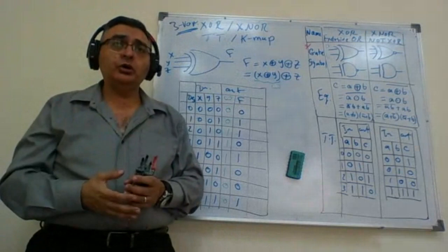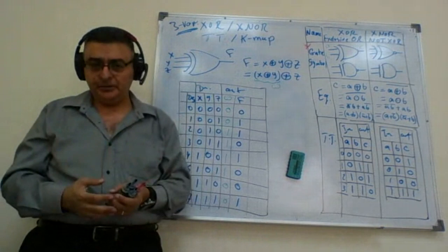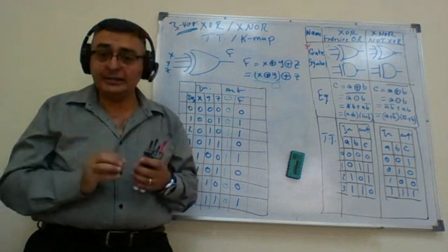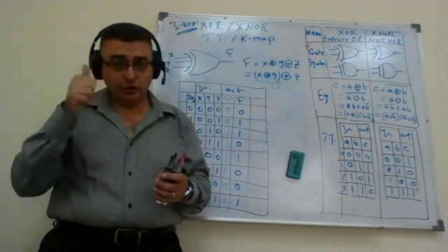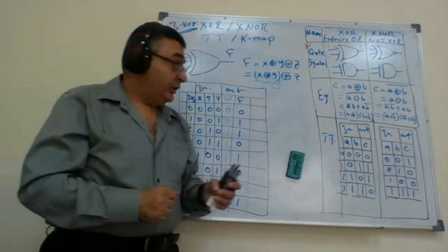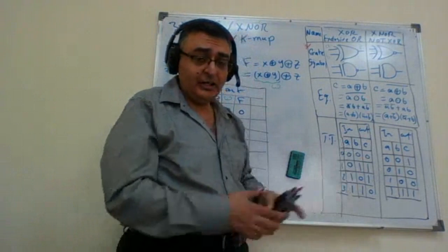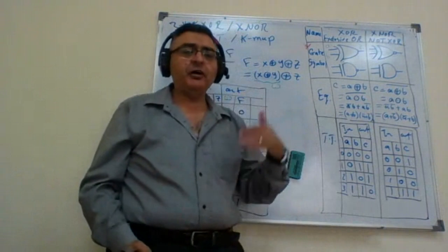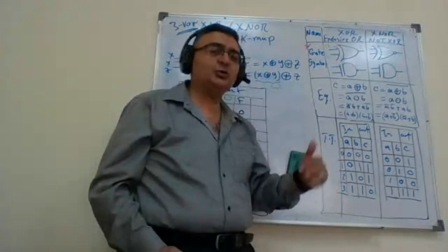However, XOR can also be viewed with another explanation. The XOR actually recognizes the odd number of ones between the inputs. And this is clear here. If I have an even number of ones, the XOR is 0. If I have an odd number of ones in the inputs, the XOR will be 1.